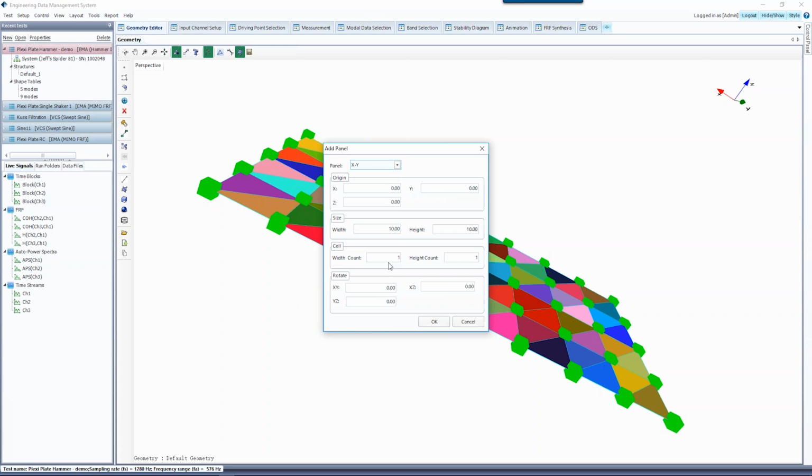Let's just do it. So you can see a line has been added. That's a beam structure, or component, being added. And if you say, oops, I made a mistake, you can go back to undo the previous operation. Or if you deleted something by accident, you can redo it to bring it back.